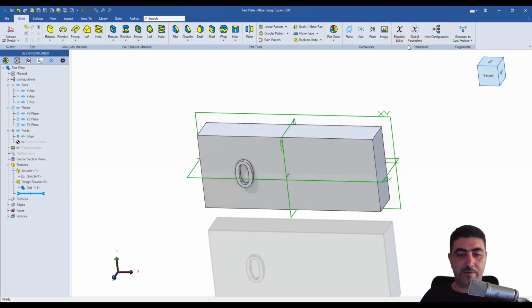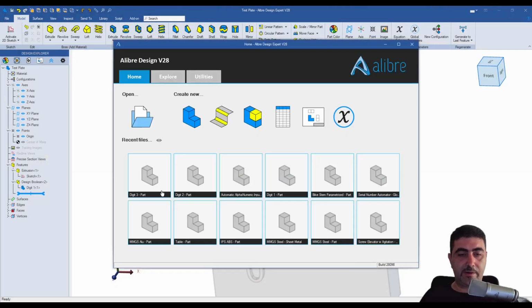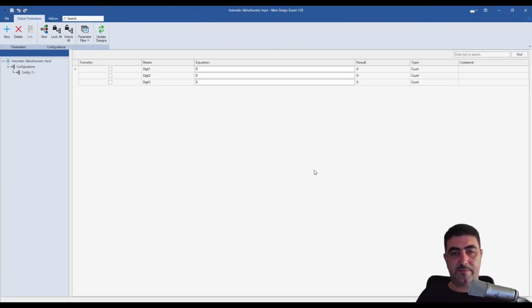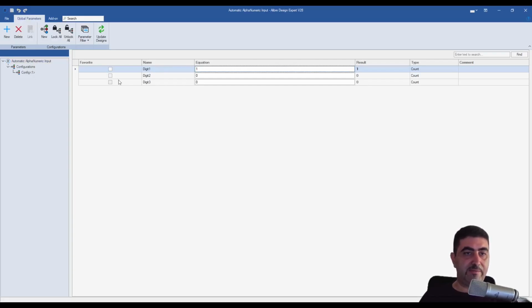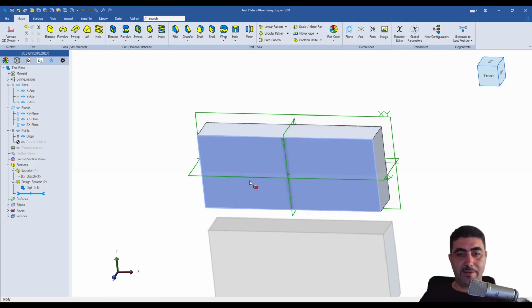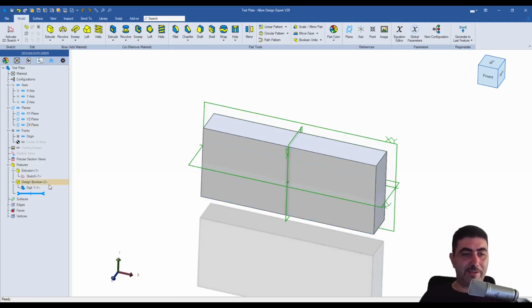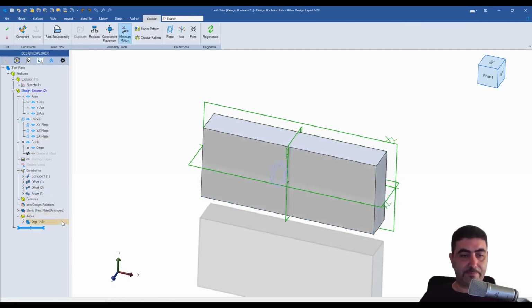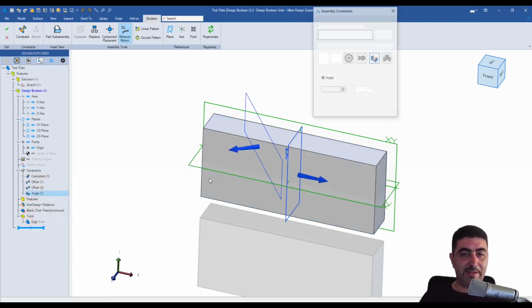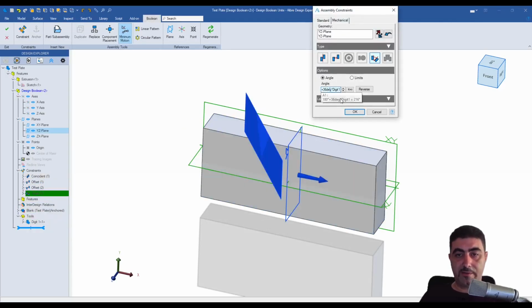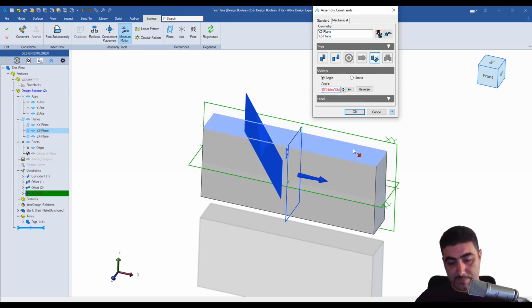If we go now into our global parameters file and make this into a 1, okay, hit enter. We save and we update. Let's go back. So we got nothing here. Okay, that tells me that in here this little symbol should have been a minus.